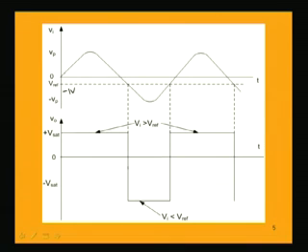So, for the whole signal up to this point, Vi is higher than V reference, which is minus 1 volt. So, if this voltage is higher than minus 1 volt, we will be getting a positive saturation voltage, which will be around 14 volt for 741 IC. This saturation voltage Vsat is obtained from 0 onwards till the point when it becomes lesser than minus 1 volt. From this point onwards, it is in the negative direction and lesser than minus 1 volt.